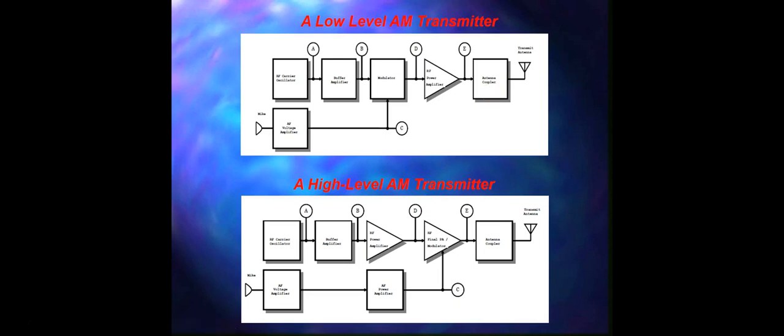For an RF power amplifier to function correctly, it must be supplied with a load resistance equal to that for which it was designed, and this may be nearly any value; around 50 ohms would be a good value, since most antennas and the transmission lines they work on have a 50 ohm characteristic resistance. But what if the radio frequency power amplifier needs to see a smaller value of resistance, maybe around 25 ohms? Then what will happen?